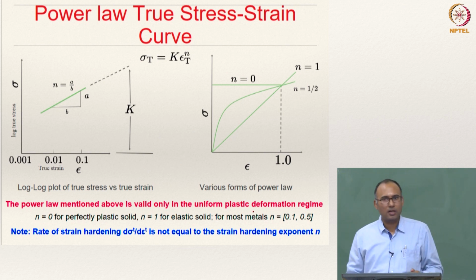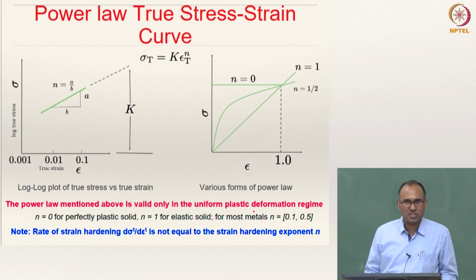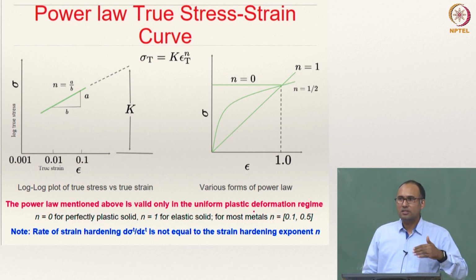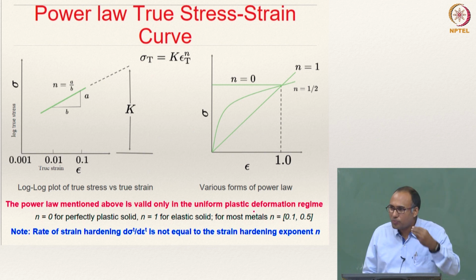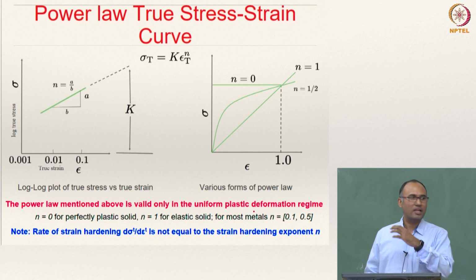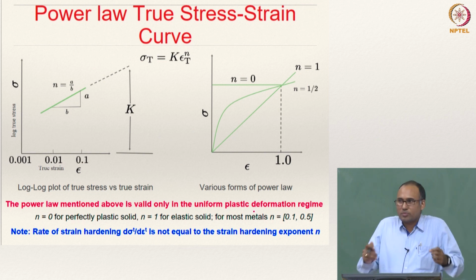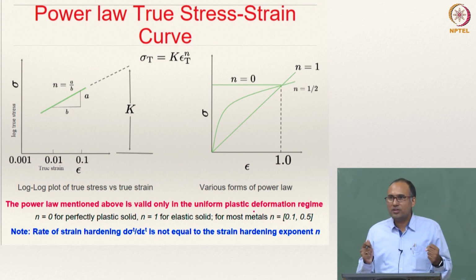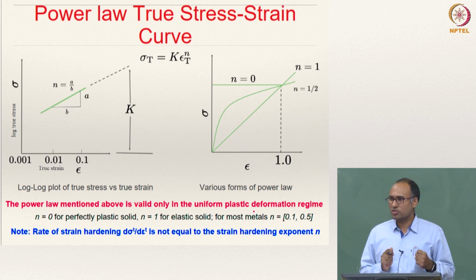And that is what we have learned about the elastic regime. And then this elastic regime is followed by a phenomenon called yielding, that means the onset of plastic deformation. That is when the dislocations in the material start moving. Until then they are not activated, right. So that means your stress is not large enough to actually cause the dislocation.